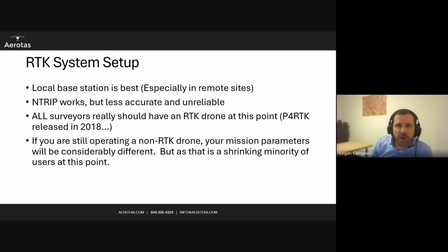Another question just came in from Josh. Do you recommend flying RTK and collecting PPK data as a backup in case of an RTK failure? Yes, that is absolutely a good and robust recommended procedure. And in fact, believe it or not, that's what a lot of drones do by default. One that does this most commonly right now is the DJI M350 with its L2 sensor. Even if you're using the DJI base station, it flies in full RTK, so you have that.